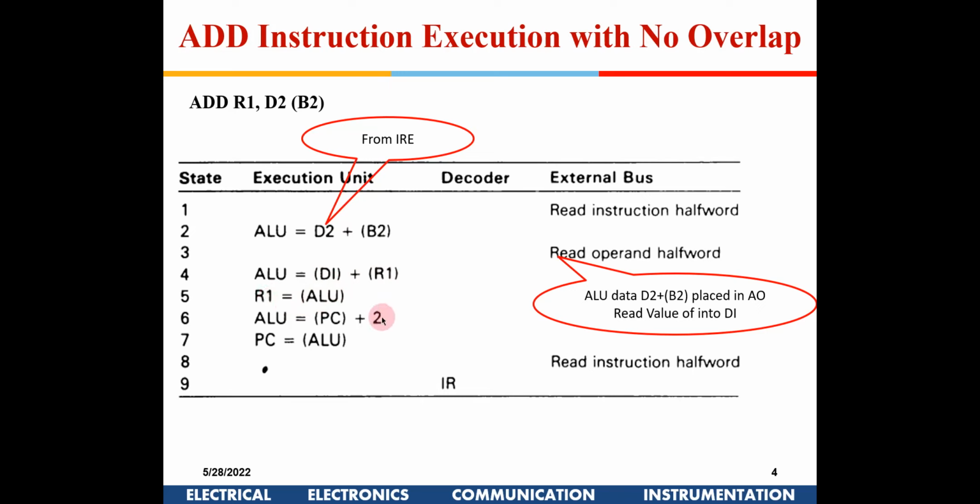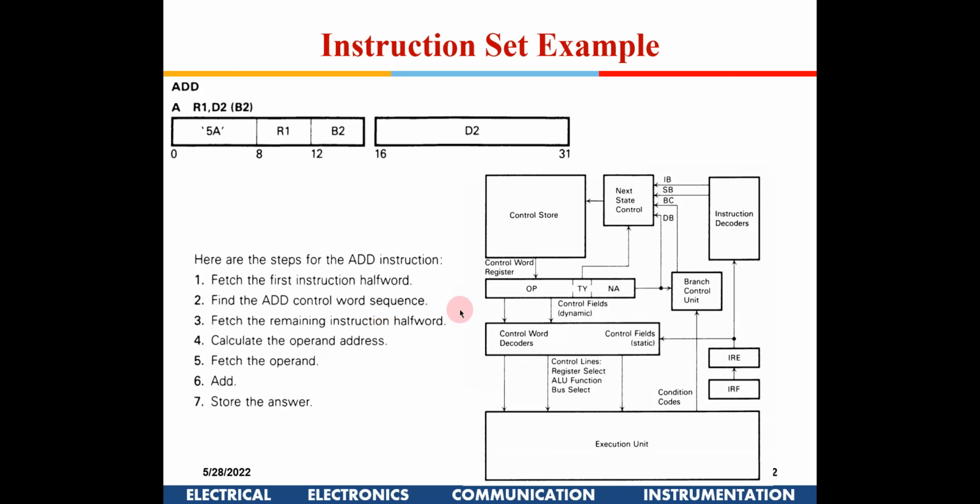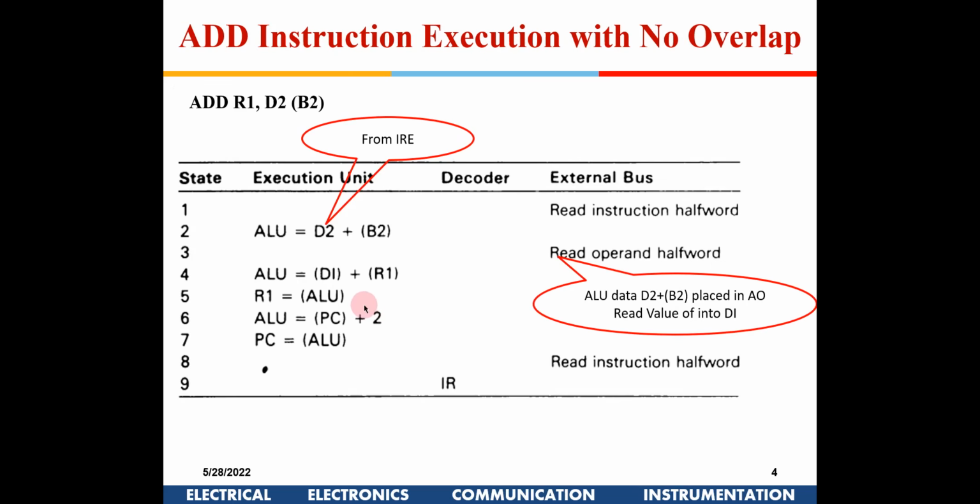Now until now we were speaking of the program counter being incremented by 1 every time. Here we are talking about 2, assuming that the instruction is a word instead of a byte. That is the reason we are writing +2 here instead of +1. So every instruction will be not a byte but a word here, and you have to keep adding +2 so that it keeps incrementing by 2. Every instruction is 2 bytes. So that is the change from the previous lecture.